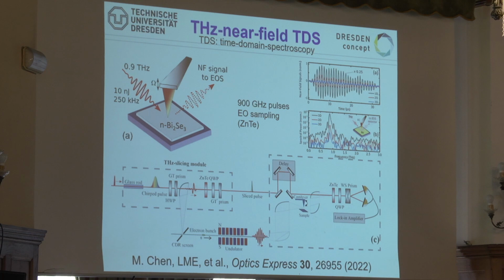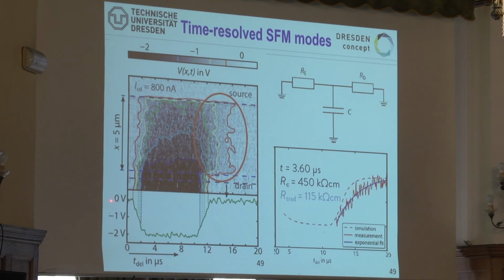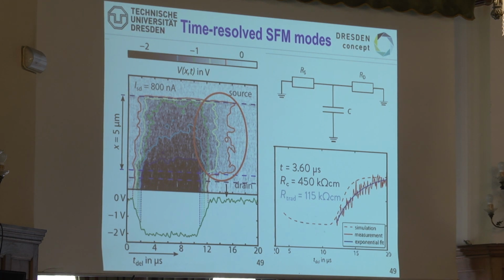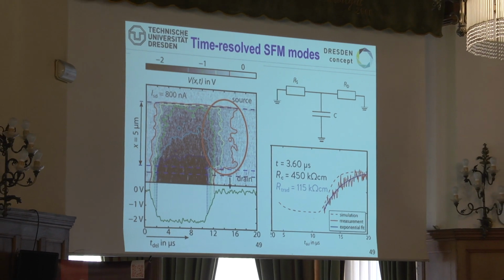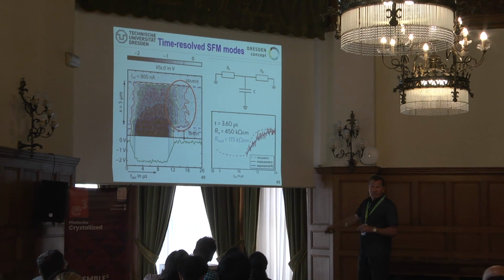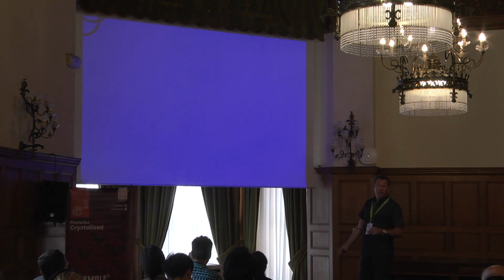You see even more, because if you turn on your gate, you say, okay, electrons, you can go in, and then you say, I'm going to shut down. Electrons, stop. No more electrons from here. Okay, barrier. And you see these electrons that are in there in a channel for about 10 to about 16, for 6 microseconds. They say, okay, we feel really happy in the pool. We don't want to get out. Okay, it's just opposite. They can't get out. They're stuck in it, and that actually means your device is dead for about 6 microseconds. So you're very slow on that.